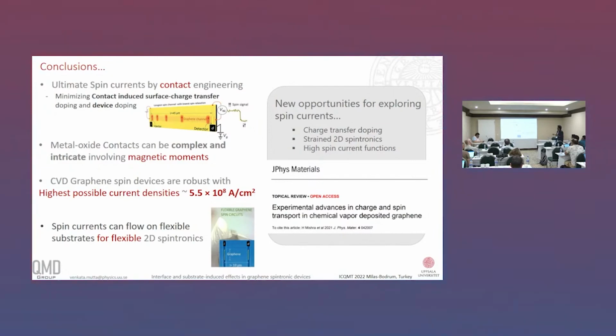They can involve magnetic moments, in addition to pinholes, even though for titanium dioxide and aluminum oxide, if we do atomic force microscopy, they both reveal the same kind of topography, which means they both can have pinholes. So it seems that magnetic moments influence, and then we also see that it's possible to push very high currents